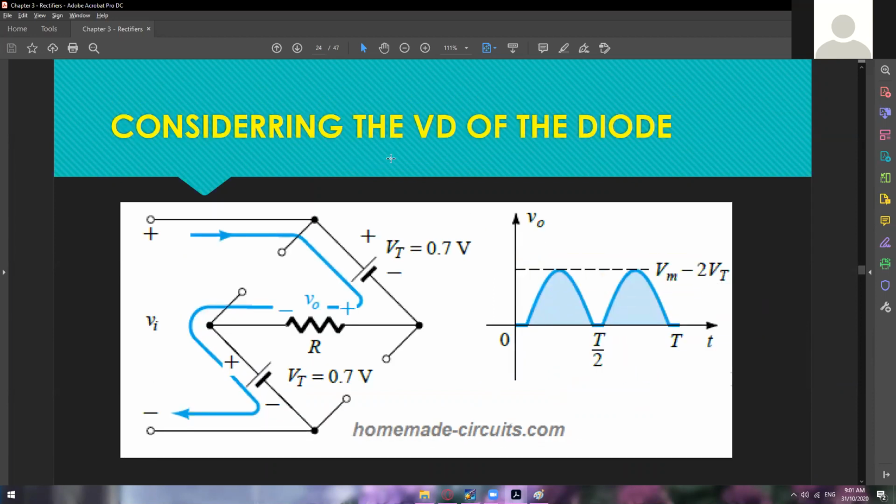Right, so considering the VD of the diode, now we're considering the diode as a silicon. So we now have to deduct the voltage threshold of the diode. As you can see right here, as it passes through our first diode, it will now deduct or consume 0.7 volts going through to our voltage output, and then as it passes through our second diode, it will again deduct 0.7 volts. So we have this kind of setup. Let's say everything is silicon, then we could just say Vm minus 2 Vt. That is if those two diodes are the same.